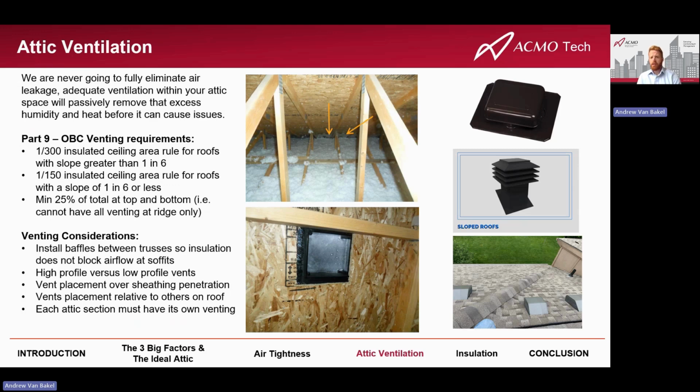One of the most important things to consider is baffles. That's making sure your attic insulation is not blocking those soffit vents. So install baffles between trusses. They can be pieces of plastic or cardboard that allow that airflow to come in from the outside into your attic space.